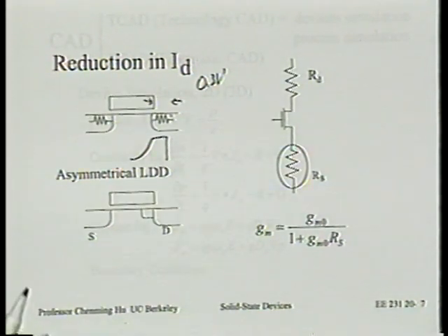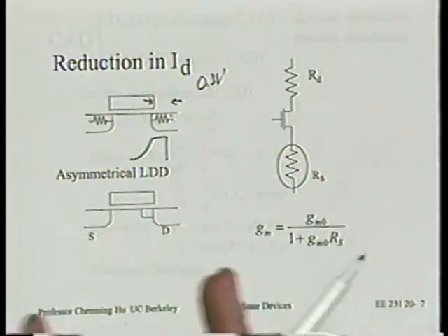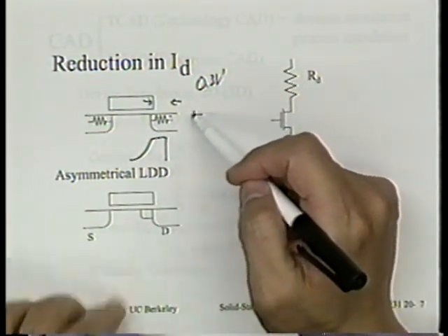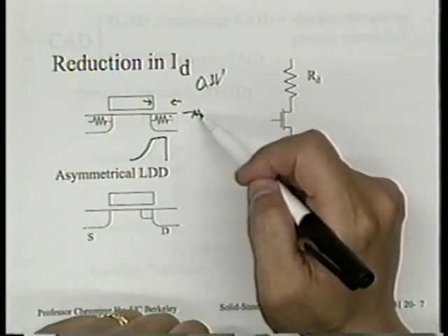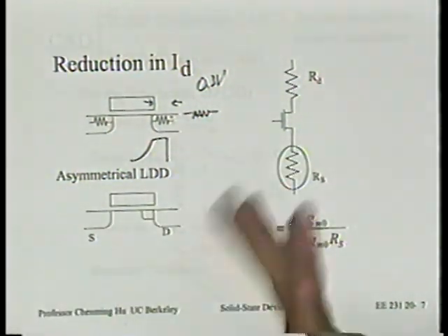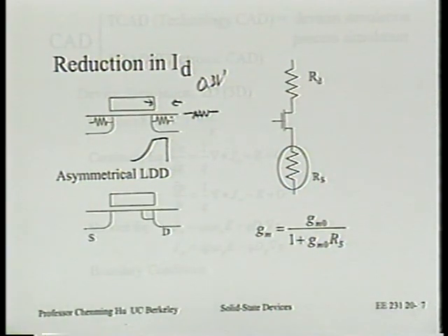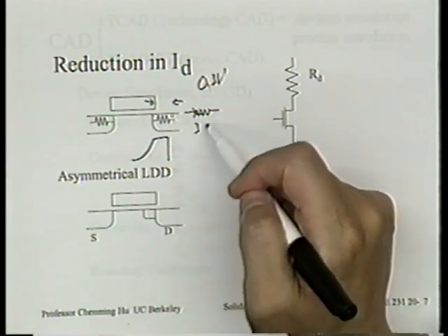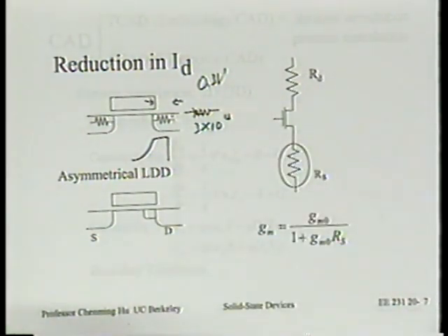If you try to put that field in a resistor, think about it. Resistor, like a well resistor, forget about the problem of creating that. Just say we use implant to create a resistor. But by resistor, at least you should imply you're dealing with the ohmic region. It's called resistor, right? In the ohmic region, we can never apply a field larger than 3E4. Beyond that it's no longer a resistor.